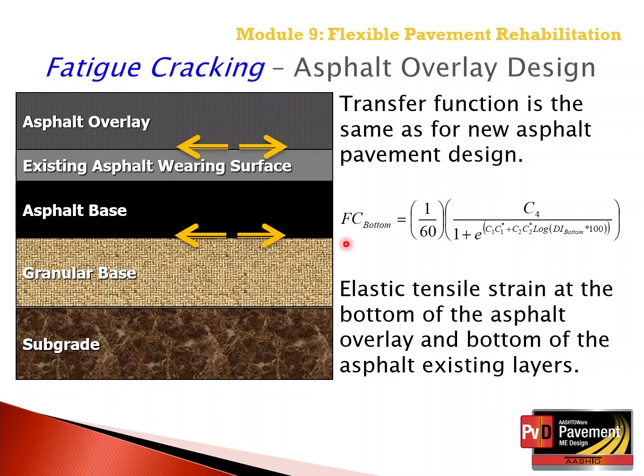The transfer function is shown on the slide, and it is used both for the asphalt overlay as well as the existing asphalt layers, because the existing asphalt layers already have damage, while the asphalt overlay does not.